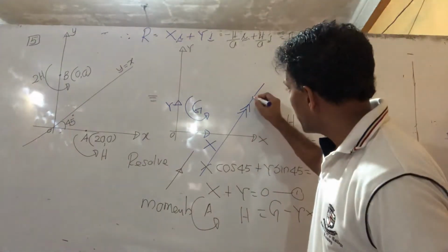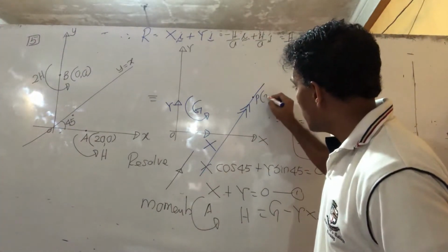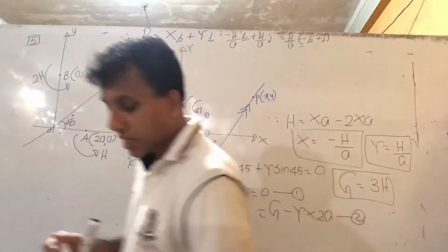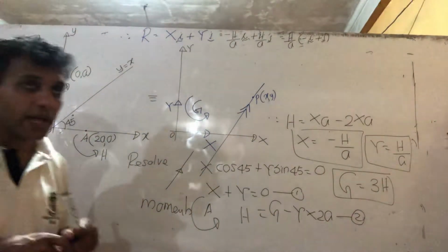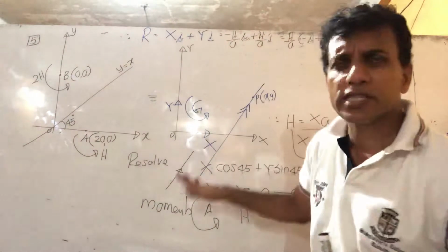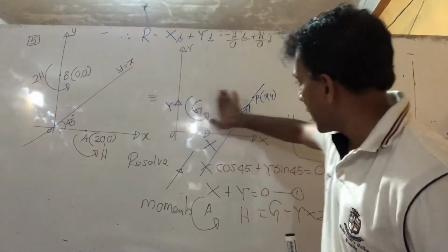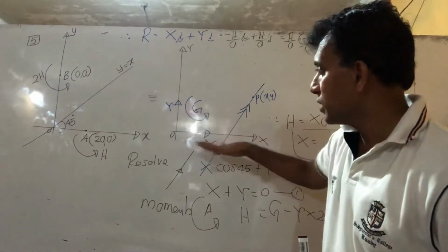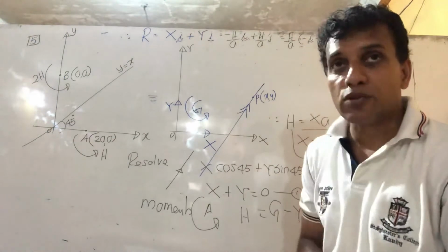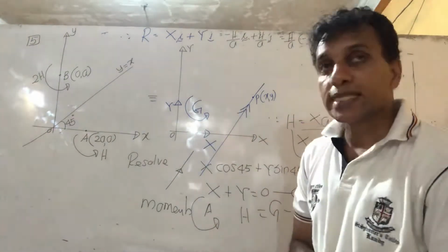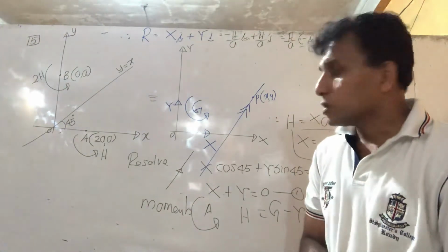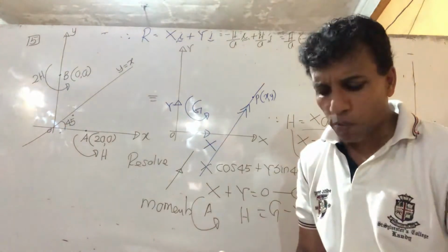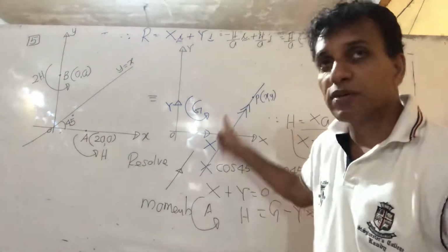So if I take a point P here and mark x comma y, we build up an equation in terms of x comma y, and that's the answer. What do I mean by x comma y, point P? You can take any point along this line. From the origin, x distance, y distance, right? Then take moments about the point P. Write the moment theorem: the algebraic summation of all the moments equals the resultant moment. The resultant passes through this line, so it is 0, right?